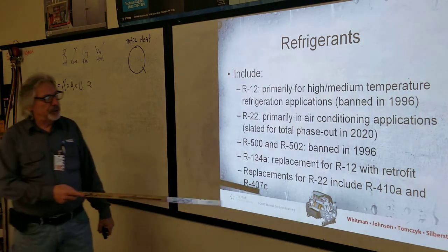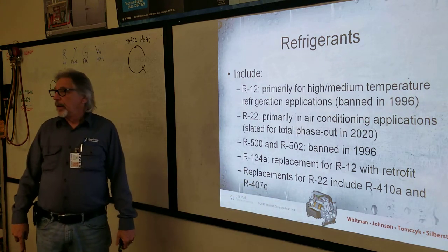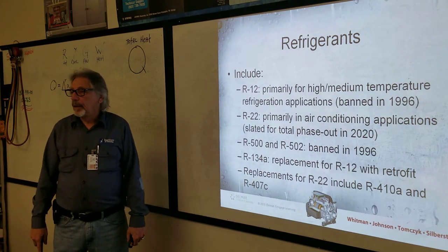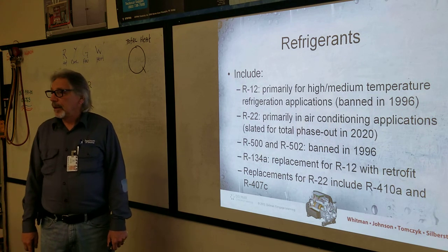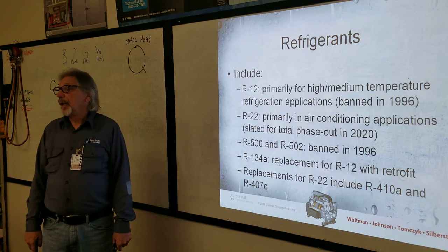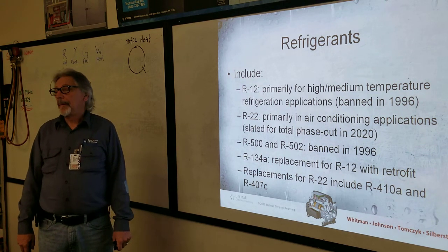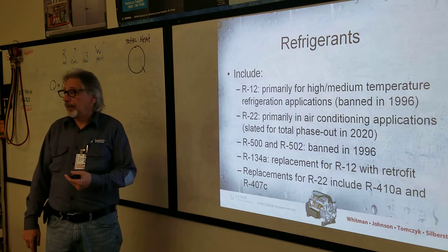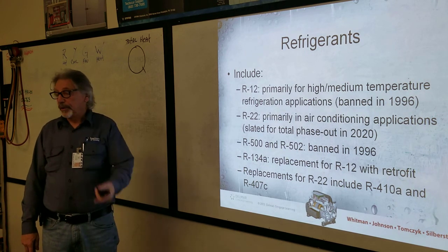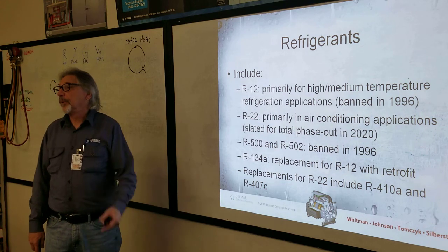Because the R22. How long is the process of dumping the oil out? Is it like an hour, half an hour? You gotta pull that, you gotta unsolder it and unbolt it. Pull it out, turn it upside down, dump all the oil out, measure it, and then you measure whatever you took out and you put back in.